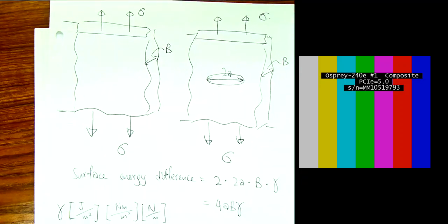So remember, keep the problem that we are trying to solve in mind. We have this issue of stress concentration around the flaw, right? And what Inglis did is that he predicted an infinite stress at the crack tip. Now that is pretty difficult to digest and to accept, that we have infinite stress at the crack tip, but that is explicitly appearing in the fracture strength result that he derived.